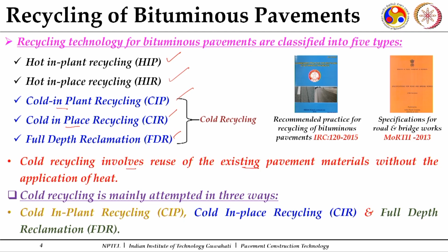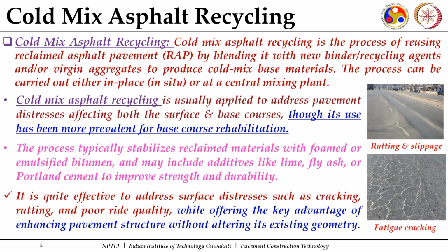It is also similar to in situ cold recycling, but with some specific considerations that we will discuss. Both full depth reclamation and cold in place recycling are done in situ. So, cold recycling is mainly attempted in three ways: cold in plant recycling, cold in place recycling and full depth reclamation. Both cold in place recycling and full depth reclamation are in situ recycling.